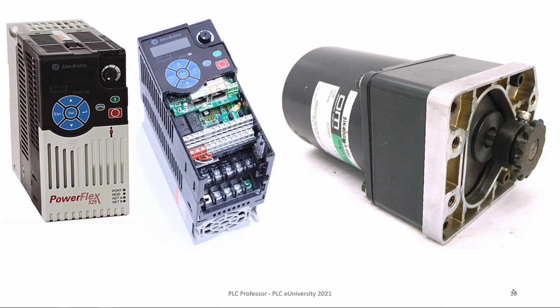Now, remember I mentioned that you may not want the conveyors to jerk when they start or jerk when they stop. They do sell something called a soft start-stop. It's kind of like a variable frequency drive, except that it ramps up to one set speed and then ramps back down to off. So it gives you the ability to start it and slowly bring it up to speed and then slowly bring it down to a stop.